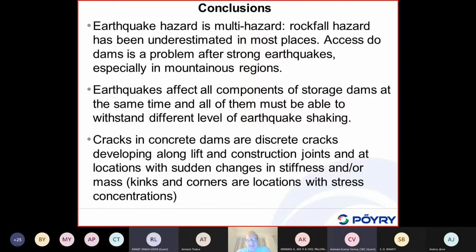Well, they are usually safer, but as I've shown in a tunnel, for example, the tunnel portals are the weak points, and I would say in tunnels, the weak points are also where you encountered problems during the excavation of the tunnels. Okay, these are also points one should have a look at if you check the earthquake safety of such structures.